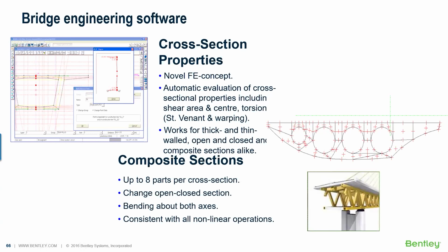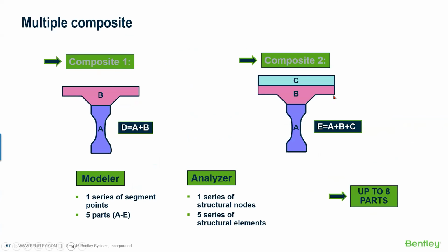Okay, in this software, the cross-section properties, so we have a two-step analysis. The cross-section by itself uses a 2D mesh of finite elements, so we can take into account local stresses, okay? We can have also composite section.